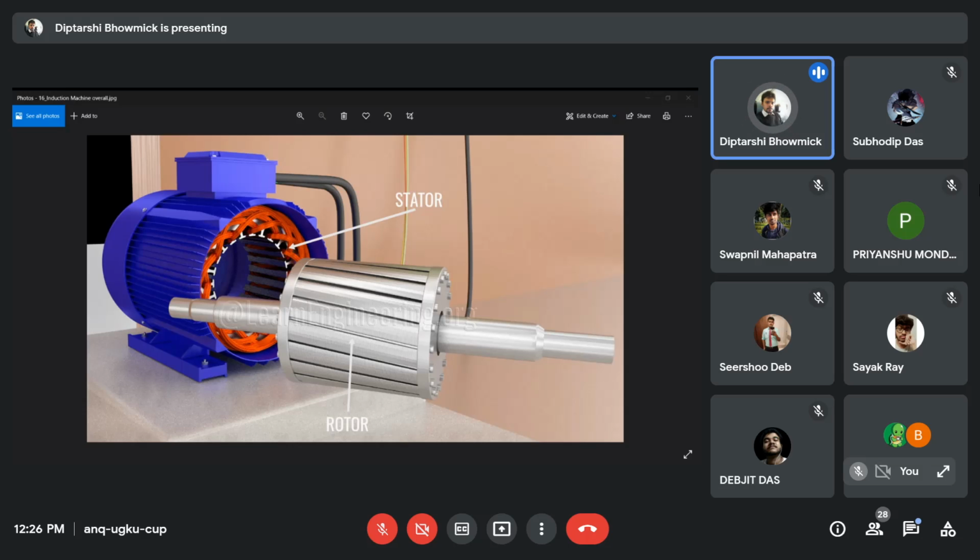So these are the nameplate data. Whatever we have told till now are the nameplate data for the squirrel cage induction motor. All these things are normally specified in the nameplate, but some may not be specified, like the number of poles, the temperature rise, or maybe the duty cycle. It may or may not be specified. But the maker's name, the rated output, rated voltage, and speed are the basic things that should be mentioned in the nameplate.